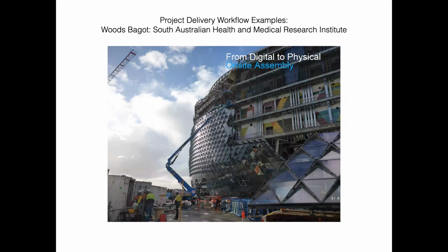So you can begin to see, simultaneously, or in parallel with making the curtain wall, they were pouring the frame, getting those slabs in. You can see there's all these clips and things like that to hang the facade onto, and that's modern day construction these days mostly, right? So in this case, it wouldn't make sense to get thousands or even millions of pieces that are all different on site. So what they did is they said, well, what are we going to prefabricate in the factory, and then how can we speed things up on site where you have the sun and heat and wind and dirt and grime and everything else.